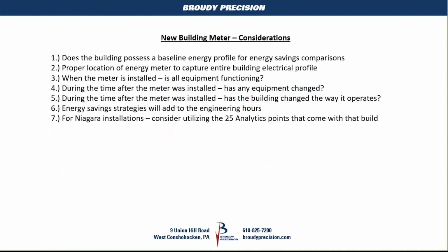And these are some of the pitfalls. I'm going to round this thing down here. A lot of times we install these energy meters into buildings, and other than the utility bills that have come in from our electrical utility, whether that's PSE&G, PECO, Delmarva, whoever the utility is, nobody really has kept an energy profile of what you're putting a meter on. That's what I mean when I say baseline.